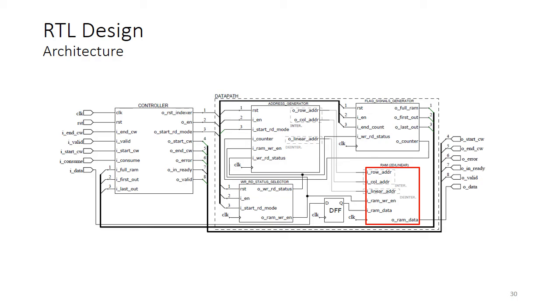On the other hand, as the interleaver requires row-wise direction during frame reception and the total number of columns is not known beforehand, then 2D RAM does not help at all. For that case, a linear RAM was used, and the address generator is responsible for calculating the index hops to implement the interleaver function.